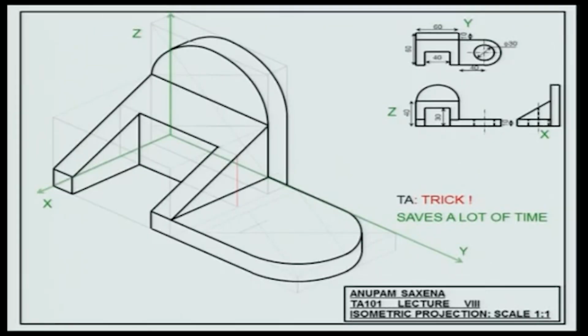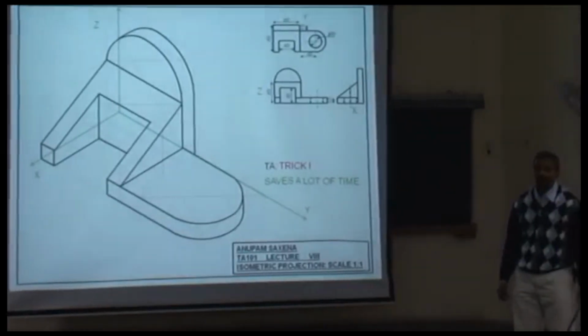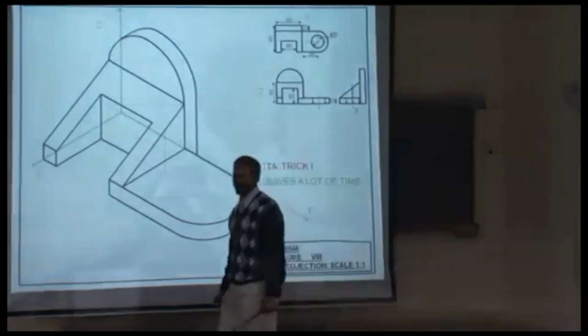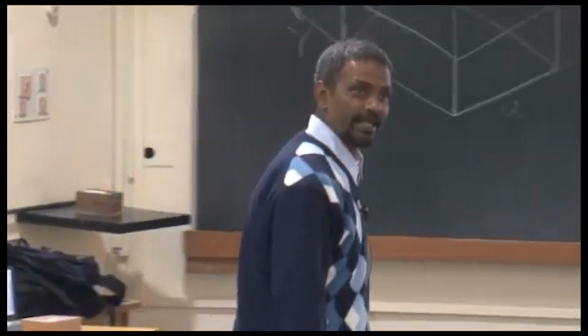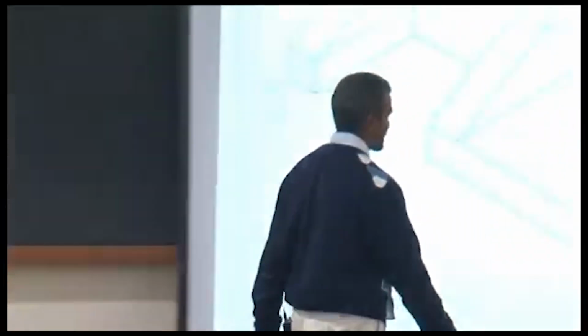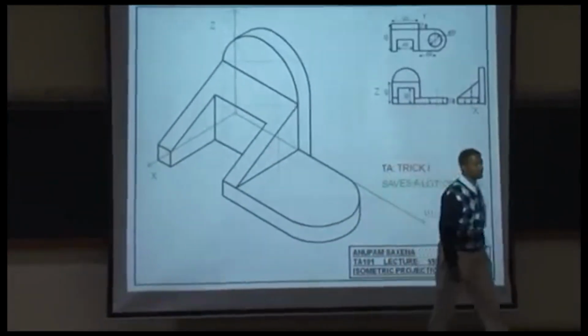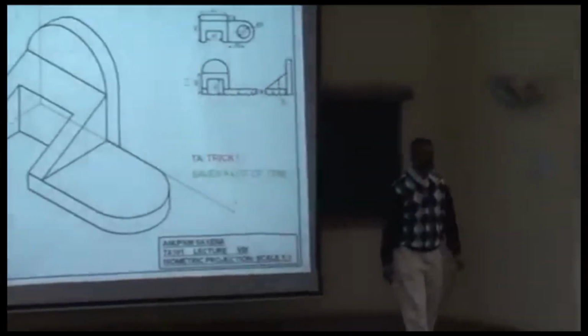Are you with me? Do you think now it's going to be easy for you to draw the ellipse, or rather ellipses, corresponding to this void, this circle? All you need to do is locate the bounding rhombus, same method, four-center method, get the ellipse.